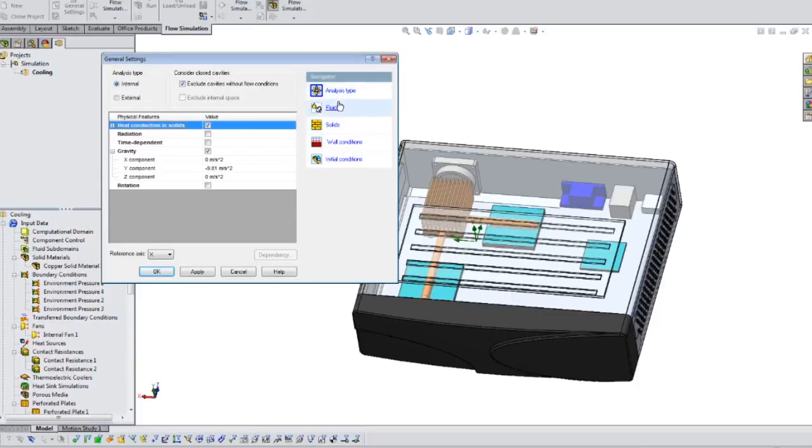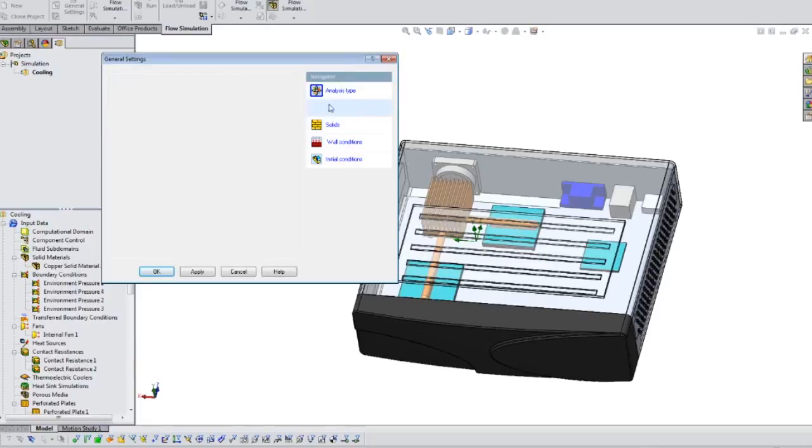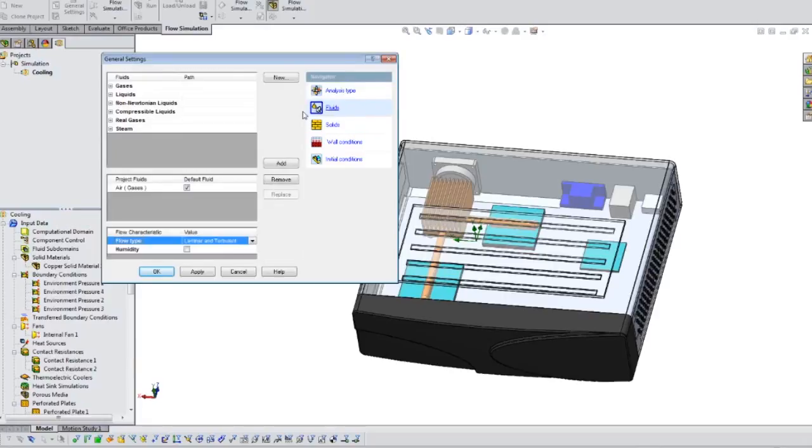I think one of the big building blocks of SolidWorks Flow Simulation is that it's fully integrated into the SolidWorks environment. With some other tools, you may have to export your SolidWorks model and run the analysis there. If you need to make a change, you go back to SolidWorks, make those modifications, then push it back out to the other tool and reset up your analysis. By being completely inside the SolidWorks interface, it means that if you know how to use SolidWorks, you probably can use SolidWorks Flow Simulation. Second, it's always watching for your SolidWorks model to change so that it can then update your SolidWorks Flow Simulation.